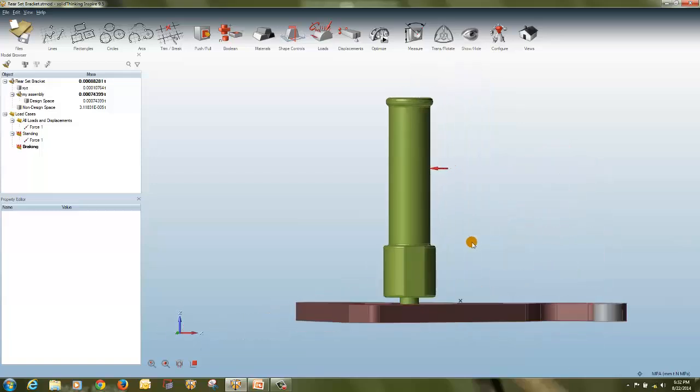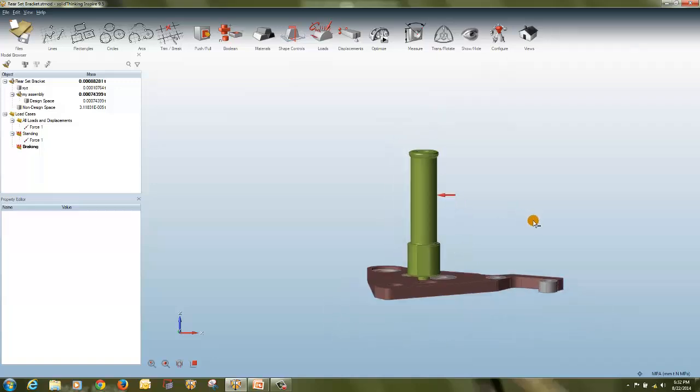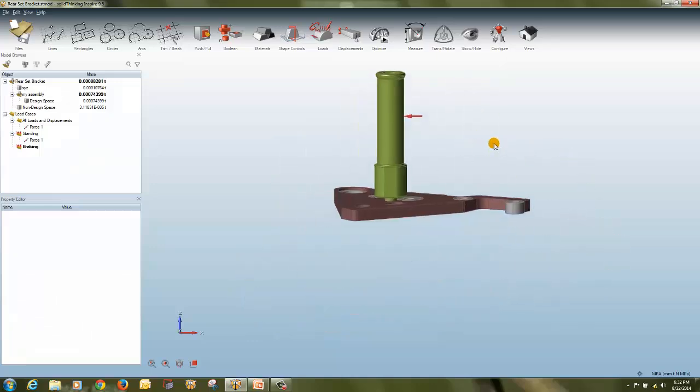Scroll up and scroll down will help you to zoom in and zoom out, and shift plus right mouse button will help you to pan the model. This is the grid movement selections, which will help you to align the components with other components. So make sure it's all ticked. This option will help you to select the unit system which you want. Whatever unit system you select, everything will change automatically. You can see here, it's changing the mass.